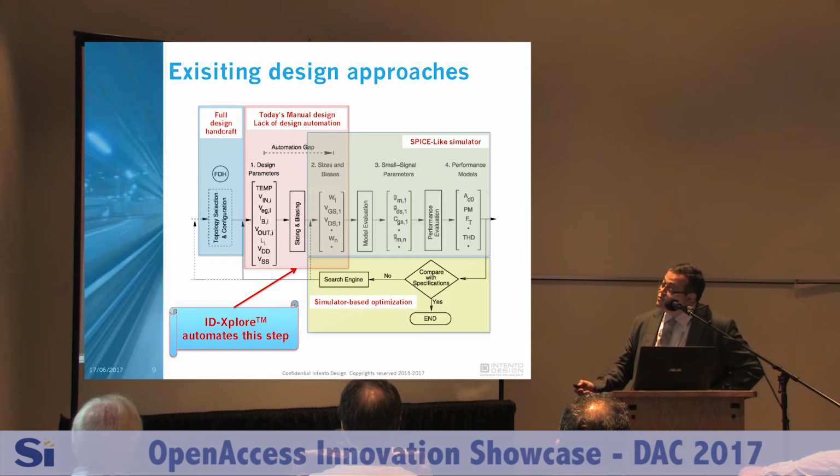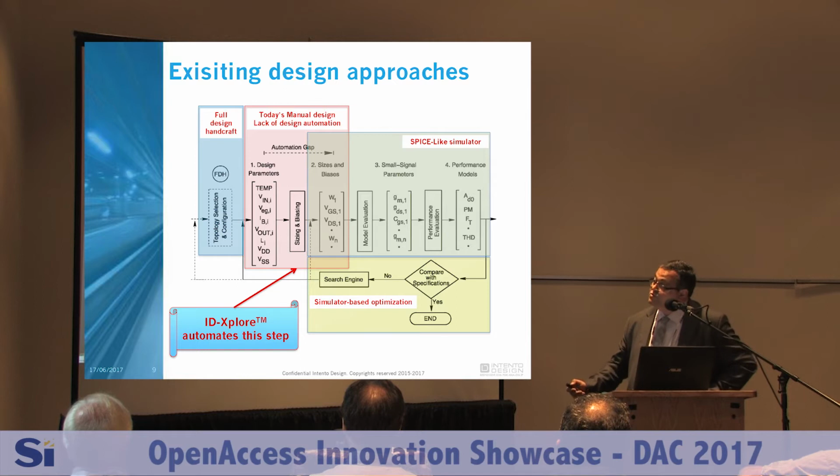So in Intento Design, we were able to develop a constraint-driven design methodology that can deduce vector 2 directly out from vector 1. The designer can select the topology, select some parameters on this topology to control, and these two pieces of information are enough to do this mapping. So we can automate the whole flow from 1 to 2, and we are much, much faster. But the particularity also of this vector is that most of the time it pushes the optimizer in the feasible region.